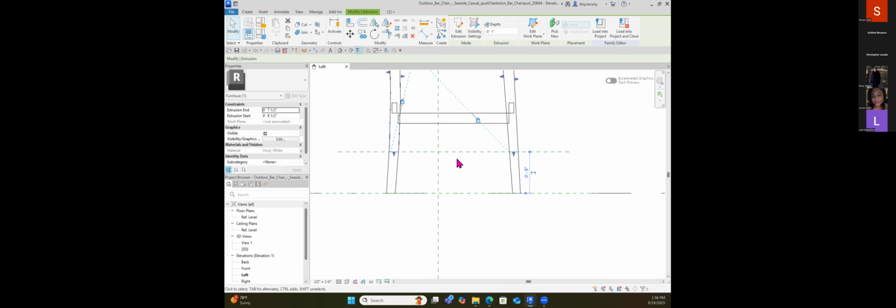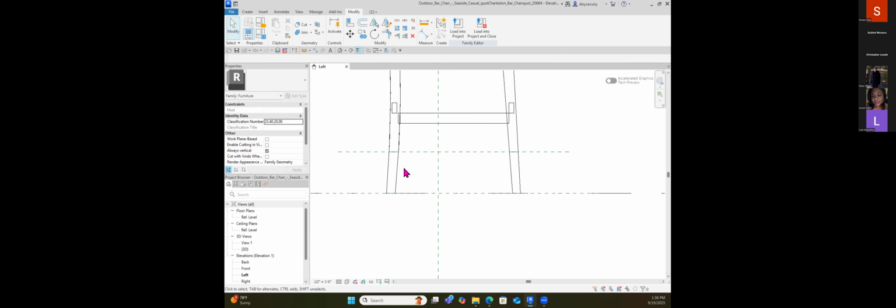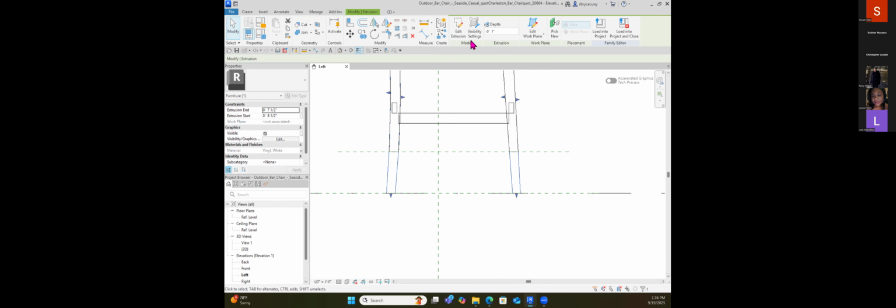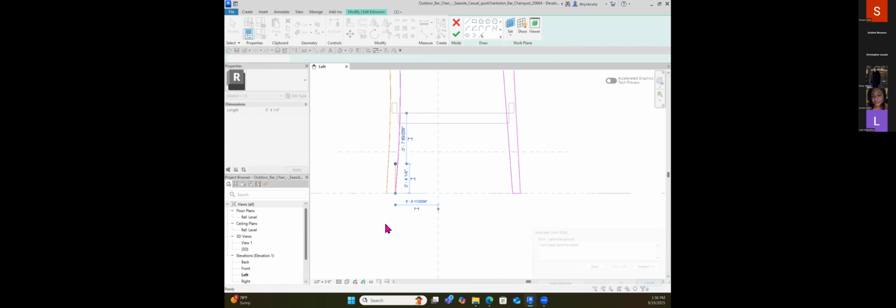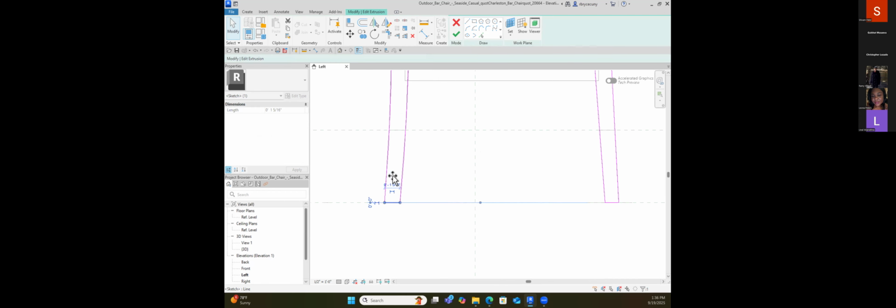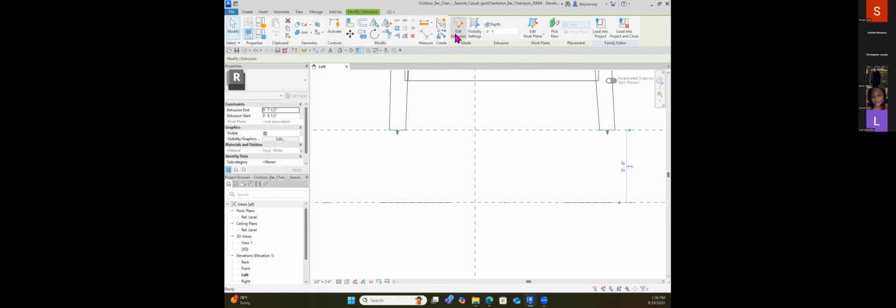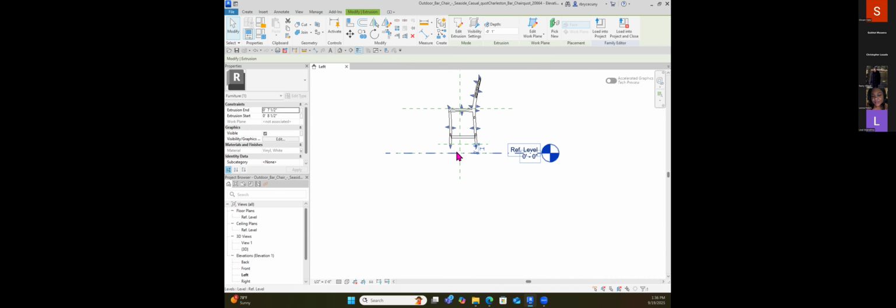Yep, we are. Okay, now we're going to edit this extrusion. So all we're doing is changing, whoops, I didn't want to do that. Drag this up to there, this up to there, and then fill it. Okay. So now the chair is 6 inches shorter.